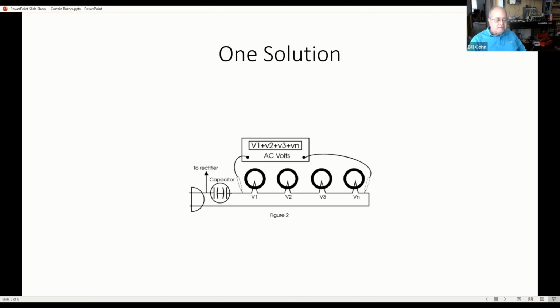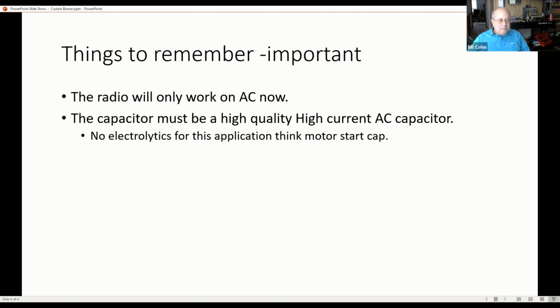I did not invent this. All this is really easily found on the internet. All you have to do is Google resistance line cord and you'll come up with about 12 different articles on how to do this particular thing. You actually have people who have spreadsheets where you can plug in the values of the tubes you put in and it'll tell you what capacitor needs to go there. But it's easily done, actually very empirically done, by using something called a decade box,